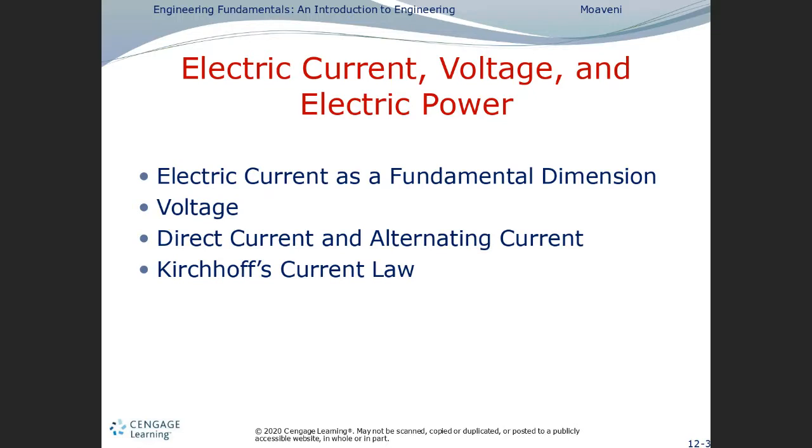And what that orifice does, or like the product that I designed with my company, is a choke, right? And so what does that choke do? That choke, it chokes the flow. It resists the flow. So it reduces the flow so that you can reduce the pressure, right? Just like in an electrical circuit, you have a resistor to reduce the voltage, to slow down the current, right?